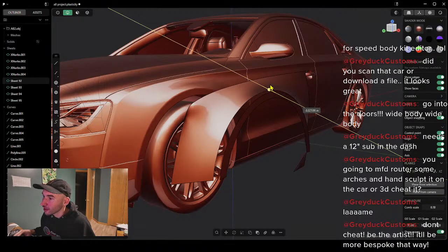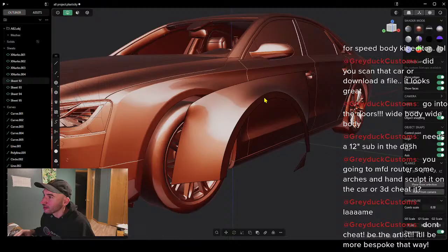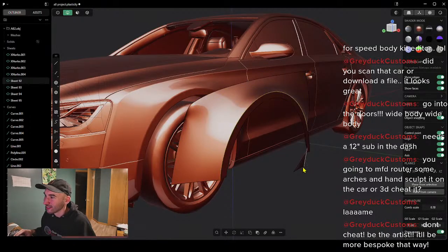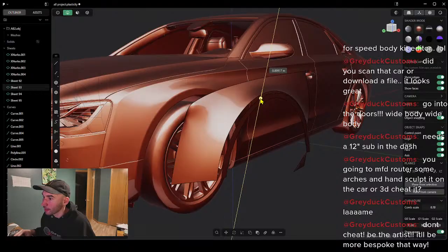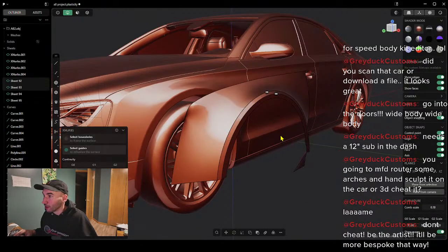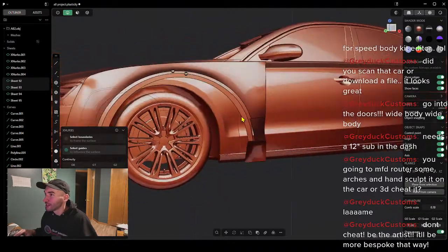Can I cut back the sheet? Okay, here we go. I'll just do this. I'll take the sheet, cut it back a little bit, and then, jeez. And then I'll take this and bring it down a little bit. There we go, that'll work. And then between these two surfaces, we'll do the X-NURBS function and then do more of a round shape. There we go, so that'll smooth it out.